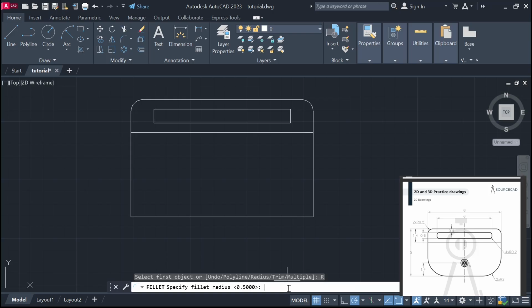You select the radius command there, and the bottom two have radii of 2. Press enter to repeat with the same radius value there. Now the inner rectangle has radii 0.2 at each of the edges.